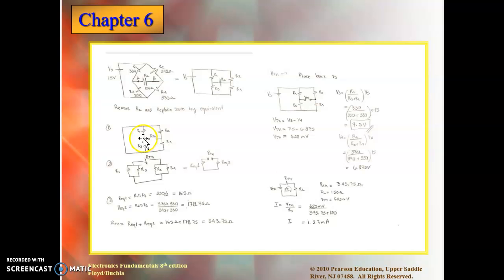So right here, I know that R3 is here, and I go across and it's connected to R1, but R3 is also connected to R1. So therefore, they are connected on this side and they are connected on that side. So they are in parallel. So R1 and R3 are in parallel because they are connected in 2 terminals.